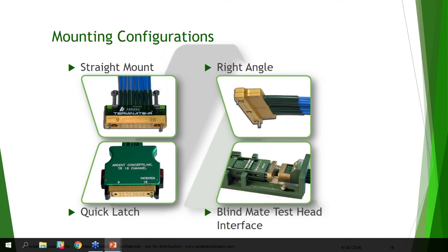This one also uses the same interface, and since this is a spring-loaded design, it compensates for board thickness variation. It works on this design from a 63 thousandths board to a 250 thousandths board. If you have a thicker board than that, then we can change the latches and make it accommodate that. But the standard design is for 60 to 250 thick board. And it'll always have enough spring force on there.